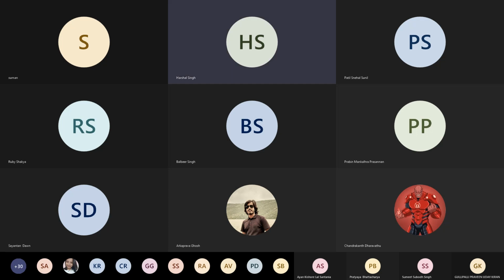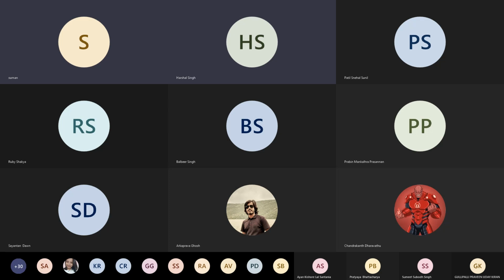Sir, after we calculated m dot x plus delta x minus m dot x, how were the higher order terms eliminated? No, they were not eliminated. They are very much there. The higher order terms will include either delta x square or delta y square or delta z square. In the x direction, it will be delta x square, cube, etc.